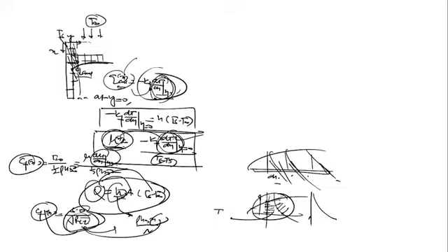At the wall, in all scenarios, random molecular motion dominates over bulk motion. So if we are able to find the temperature distribution, I should simply differentiate the temperature at y equal to 0, multiply with kf, and I can find the rate of heat transfer by conduction, and the same holds for convection.